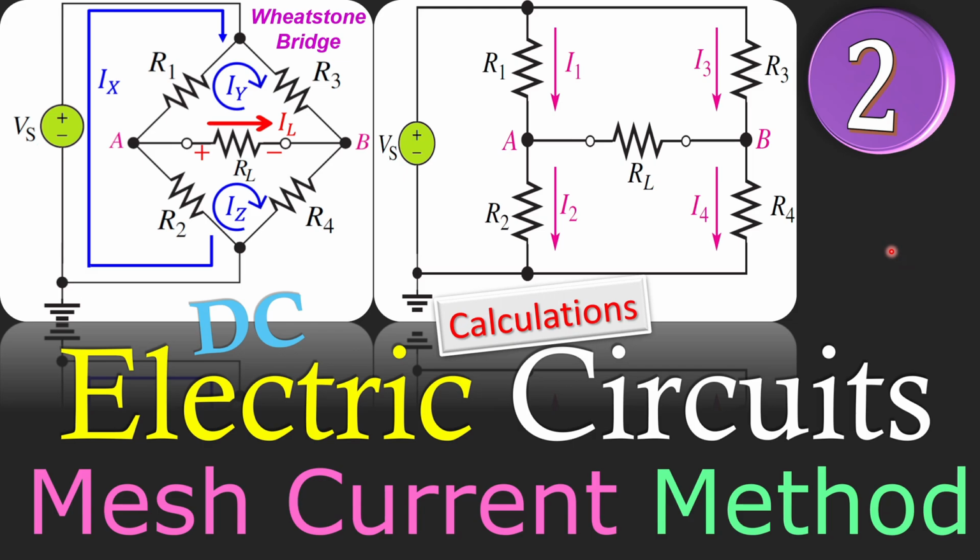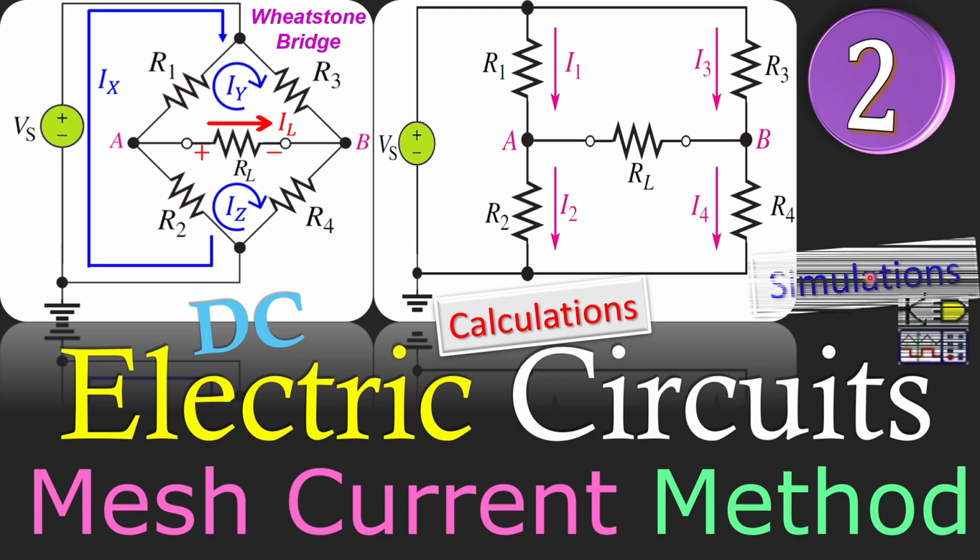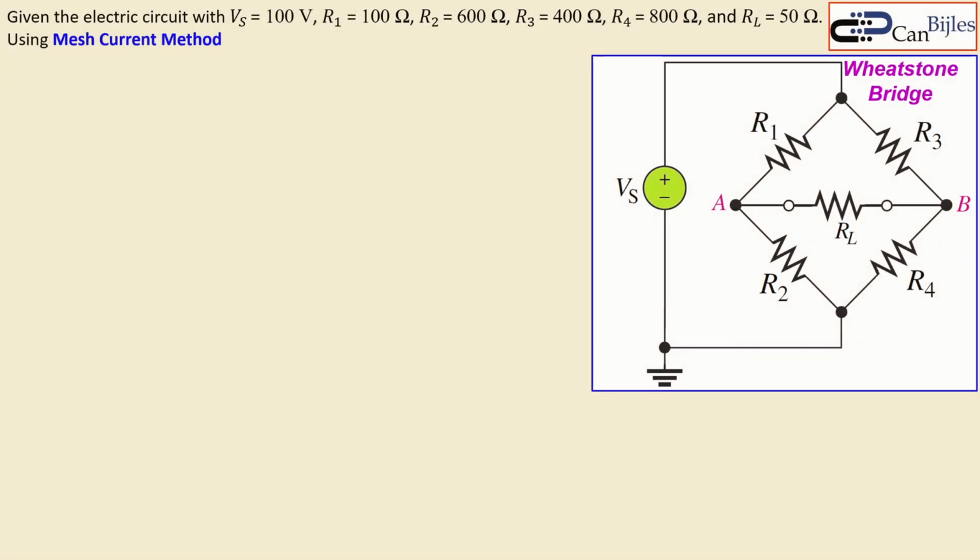Of course, we'll work out the calculations for this example step by step and also verify these in our SPICE simulations. So let's look at our example and also the values we need. Now we have the circuit here. As said, it is a Wheatstone bridge. It's actually used for, let's say, the strain gauges, all other elements to have a specific voltage across the points A and B. The voltage here is a DC voltage, so that is 100 volts. R1, R2, R3 and R4 are also given, and also the load is given. So we have 5 resistors here and 1 DC voltage source.